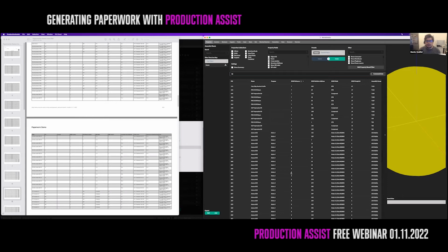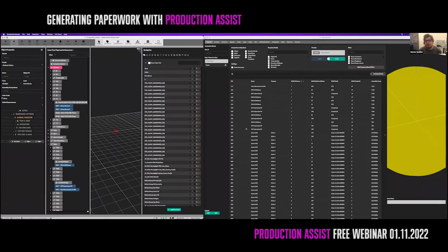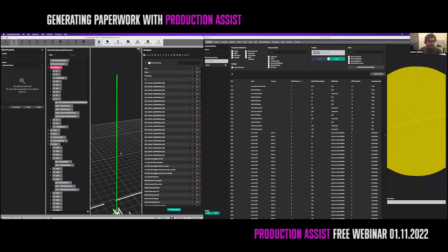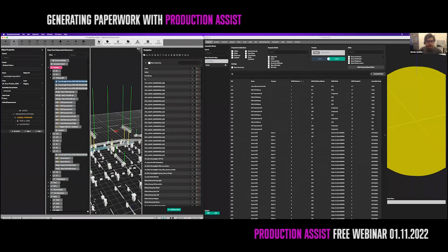So it contains all the fixtures, which will be nice for a lighting designer, but will be confusing if we actually want to give this to someone to patch this onsite, the fixture list. So for this here, the scene tree comes into play. So we move this again so that we see a little bit more of the rigs. And I want to create a power patch sheet for this specific truss line in here.